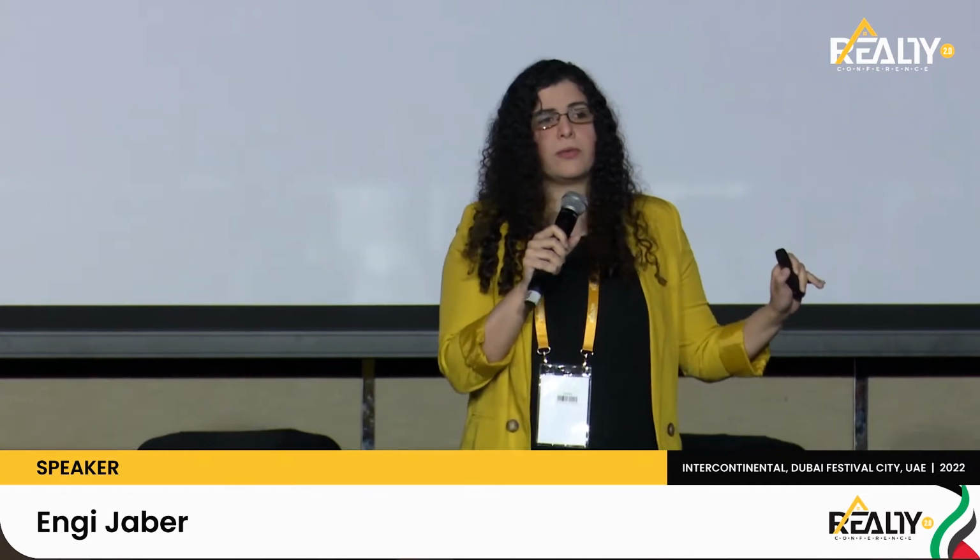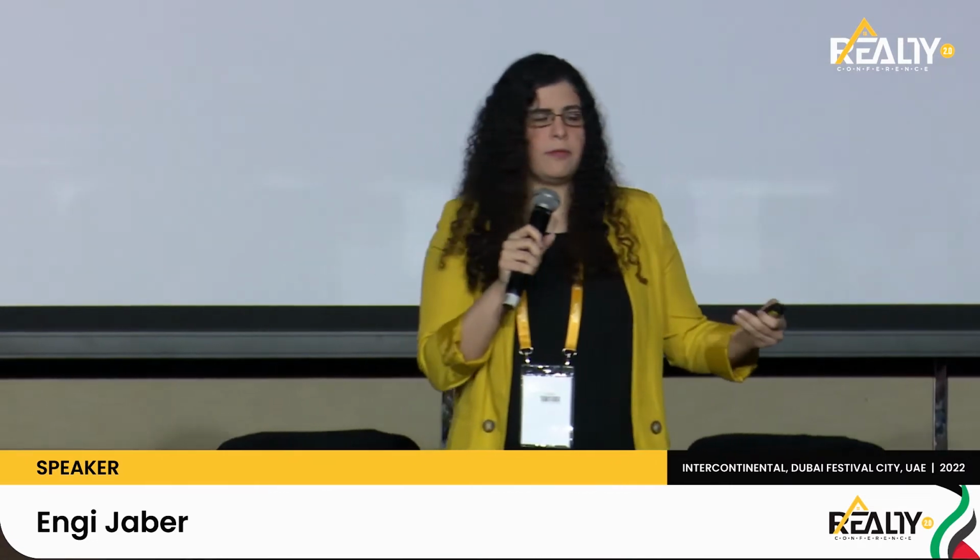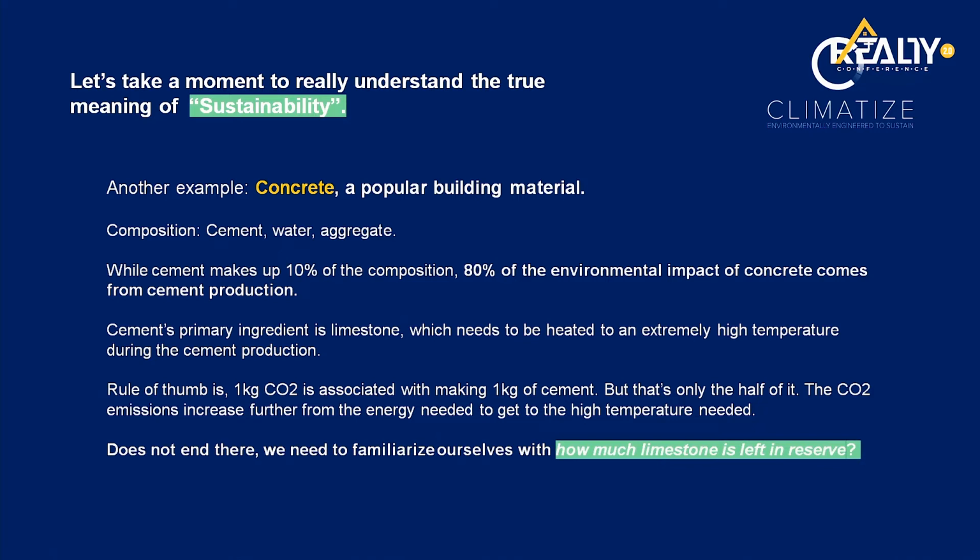And why is that? Because cement, or concrete in general, requires a lot of limestone in the process. Limestone, as a standalone resource, needs to be heated at very extreme temperatures for it to be utilized within cement production. And that drives the carbon even higher because of the embodied energy that comes with the fossil fuel burning at that high temperature. But it doesn't really end there. When we are choosing concrete, we are thereby choosing all of its byproducts.